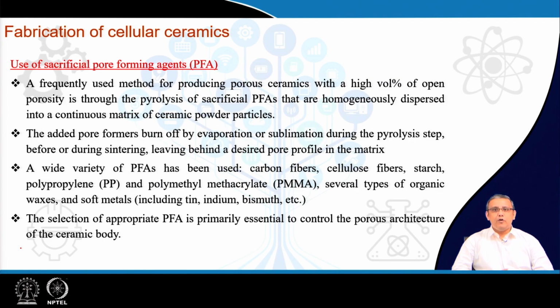Among the pore formers, as I already mentioned, there can be many materials used. Typically these materials are low melting point materials. There can also be materials like carbon fibers, cellulose fibers, starch, polypropylene, polymethyl methacrylate, and also metals like tin, indium, bismuth, etc. There are also cases where inorganic materials like sodium chloride are used.